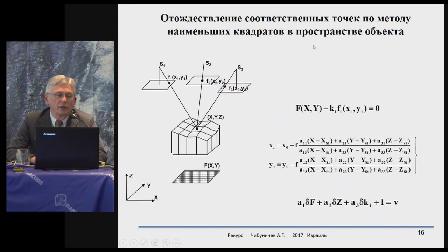this is the essence of this method. This is a digital surface model that we generated using SGM, and for each orthophoto pixel we can record this kind of equation that links orthophoto pixel brightness, a certain point on the ground and the brightnesses of this point.